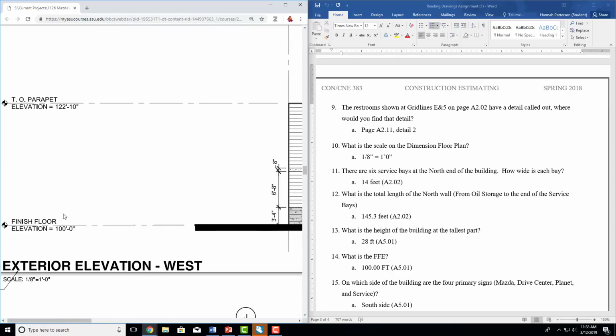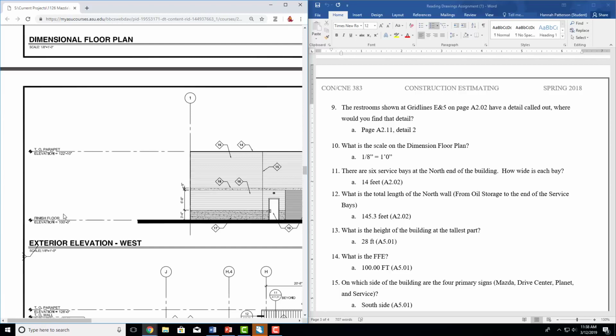Parapet wall is, if you've ever been on a roof, basically a little tiny short wall that's used as a safety measure. So that's what a parapet wall is. They're usually pretty short. It can either be used as a safety thing, so if there's a crew working up there, they don't need fall protection, or it can just be used as a little border because typically you'll have like HVAC equipment and you'll have gravel and a walkway and different stuff on a roof.